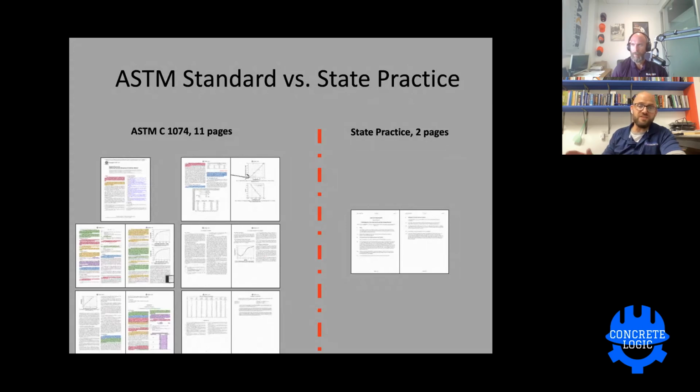The best thing that we can do is use it for mass concrete, where we do use temperature sensors, not really maturity, but temperature sensors to tell us when the temperature has gotten to a certain point where we can remove the insulation and not have to worry about cracking from mass concrete. The temperature differential between the center of mass and the external fibers. So that's long-term stuff. But for maturity, we're using it more short-term. So I guess that was the point of it. That answer your question? Okay. Yeah.